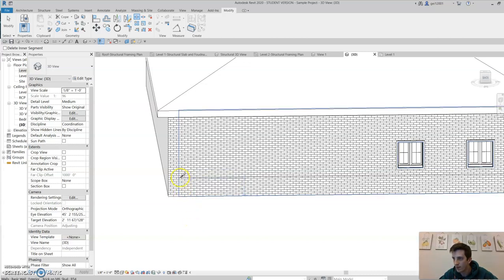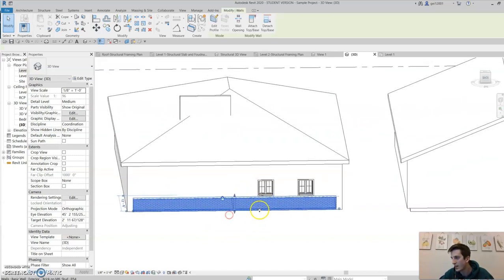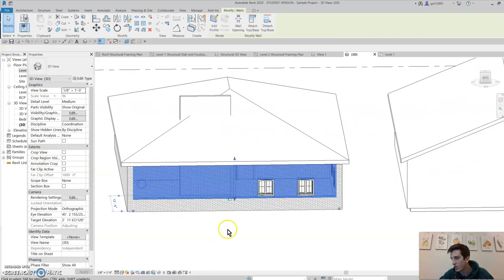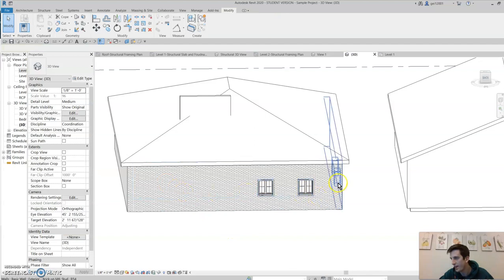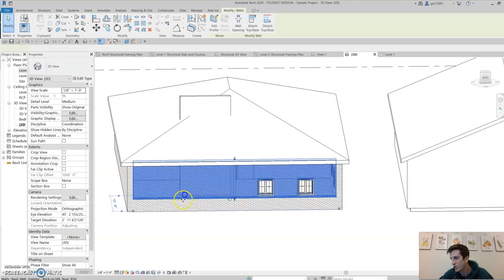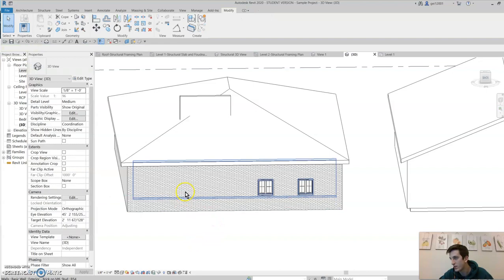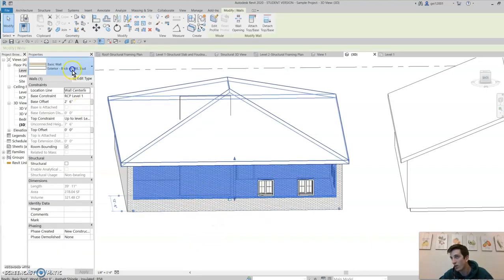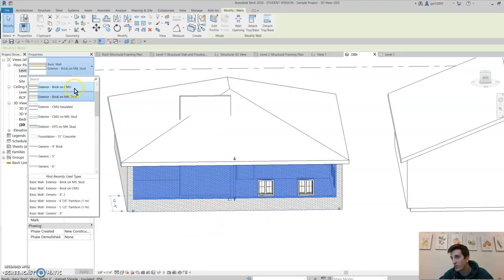When you're doing it the right way, it'll come up with a line to show you what you're splitting and where you're splitting it at. Okay, so you click that, and that finally split it the way you want it to. As you can see, I can select the wall I split below and the wall I split above. So change it into 2 wall types, which therefore makes it really easy to select one wall and to change it into a different type of material.